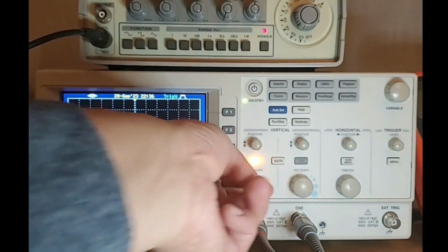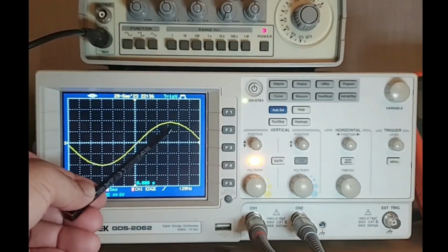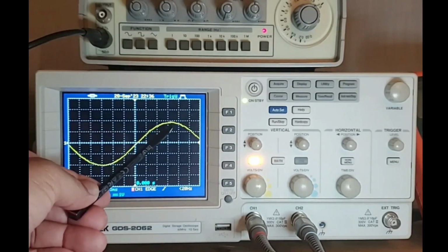So what I can do is that I will make it 2 volts per division. And now you can see that each division is 2 volts. So it's a sinusoid waveform. And you see I have one division, two divisions. So I have two divisions below the zero line. And you can see this is the zero line. This arrow represents the reference, the ground, the 0 volts. So I have negative 4 volts, and I have positive 4 volts. You see 2 plus 2, 4.